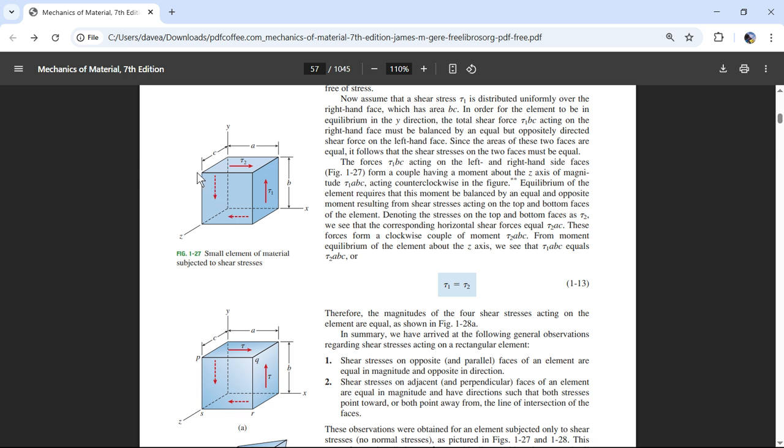I'm also going to have a shear stress on that face, because if I cut this at 45, I could stick a piece of duct tape on it and pull it perpendicular to the direction the area is facing. So the area is going to be facing at a 45. If I stick a piece of duct tape on it, I can pull perpendicular to that direction.